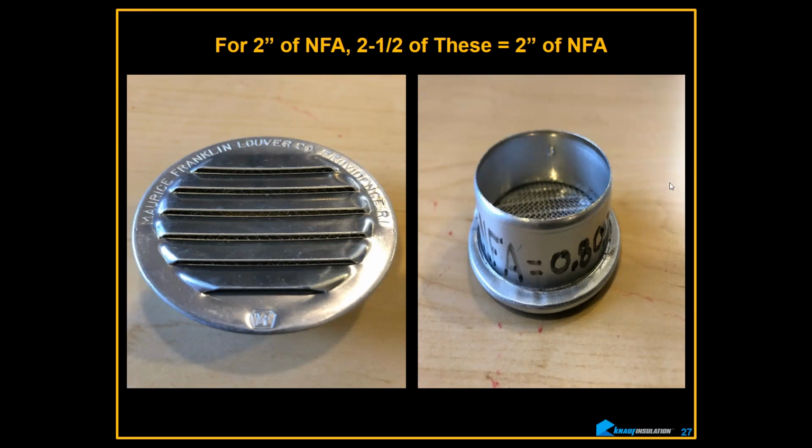You can do that a number of different ways. You can use a kraft bat. You can not use a kraft bat. You can use layers of roll goods on the outside, permeable air barriers. Tyvek is a permeable air barrier. There are a lot of different smart vapor retarders that are very expensive you can use as well. Basically, in humid climates the kraft wants to face out, and in cold climates, the kraft wants to face in towards the warm side in winter, like you said.